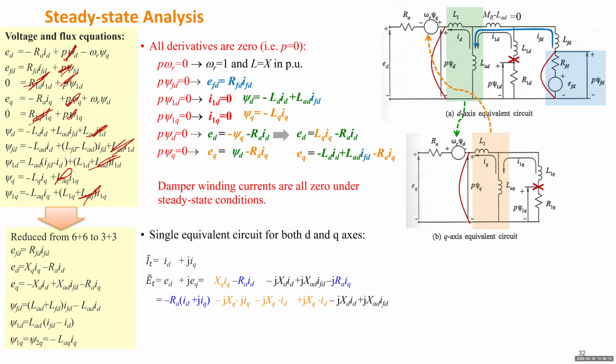So whenever we see i_q, we give it an imaginary unit. Which means we also add another imaginary unit, right? Negative j multiplied by j will be 1. So this psi_sq i_q term will become negative j psi_sq times j i_q. And the next one will create another item which is the same as j psi_sq, but we multiply by i_d. But this is a newly created item. We have to add its opposite to cancel it. So those two just cancel each other. And for anything else, it just moves here.